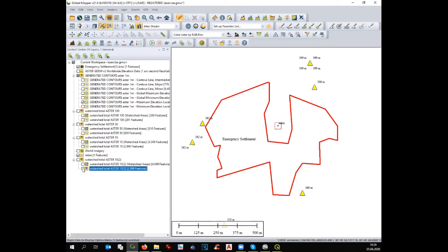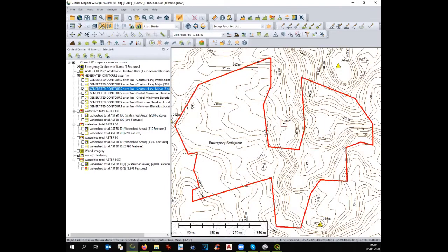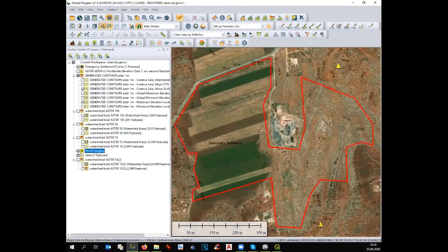Then you do the digital terrain model. You consider the elevation. You have the contour lines. You have the drainage, the natural flow of the water. And now, having the contour lines and also the picture, you can start to draw or draft your road, the internal road.